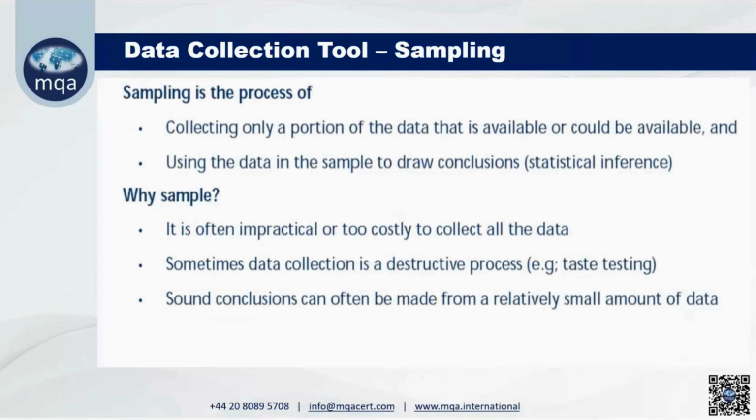So if I see that 5-6 numbers are bad, then we can conclude that the complete batch is bad, because in some cases not only five parts will be bad, the complete batch will be bad, because it is a continuous process. So in a continuous process, if one thing goes out of variation and the process is not corrected, then the remaining parts will also be rejected.